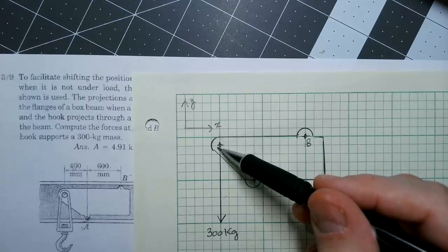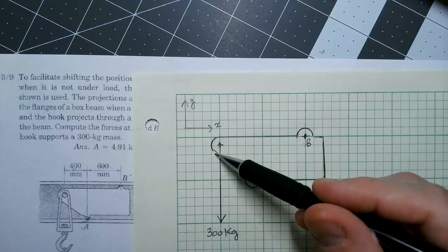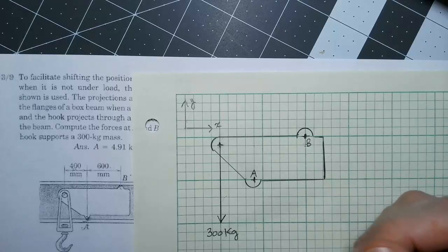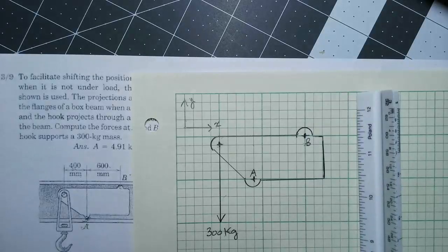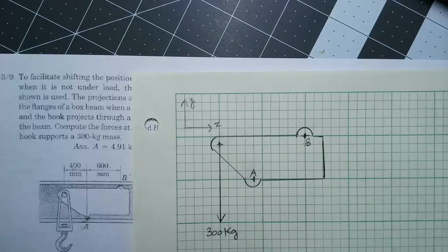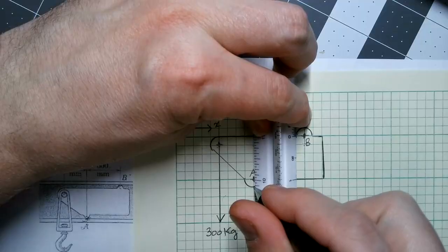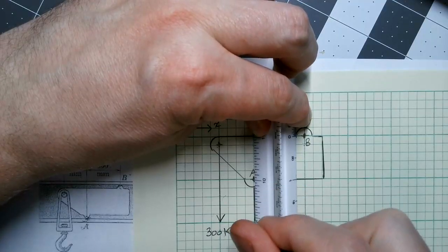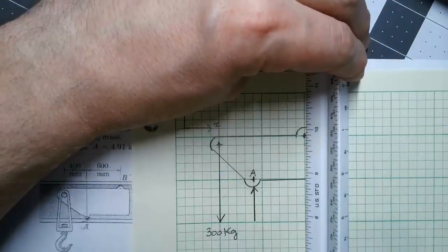So right now we know this force, and of course this is a mass right now, we're going to have to convert it to a force, but we know that this force is going in the negative y direction. Because of that, we know we have to support it with at least one positive force in the y direction. Now, either A or B are going to have the positive force. We don't necessarily know which one, so we can guess. Now, I'm going to guess correctly, and I'll tell you why it's correct, that we have an upward force, or a positive y force at A, and we have a negative force at B.